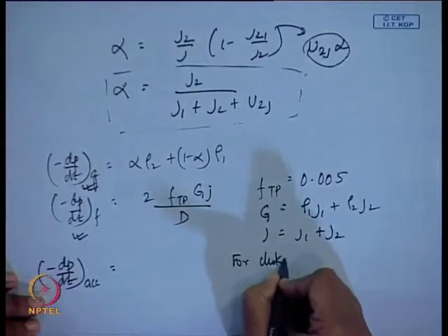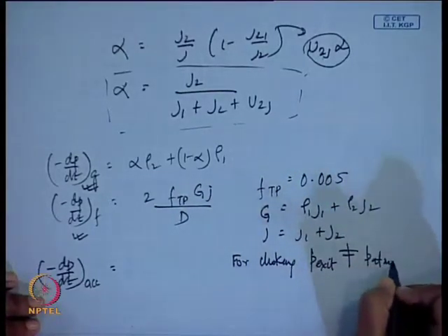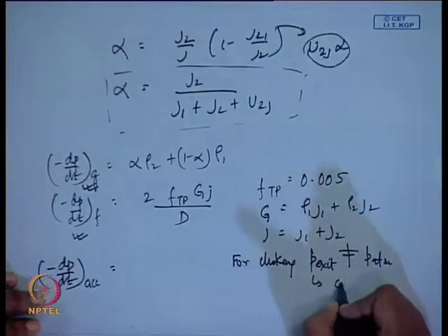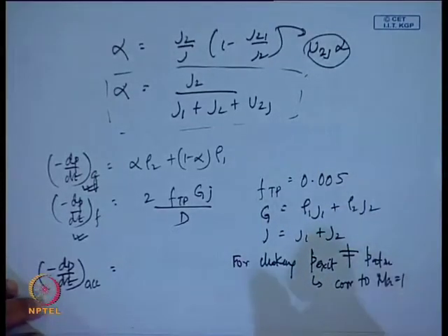In the mid-sem also I had given you a problem with a catch, and most of you could not get the catch, but remember these things are very important. So, you have to keep it in mind when you proceed: just check whether the flow corresponds to sonic flow or not, whether there is choking or not. If choking is there, for choking I will write down, P exit will not be equal to P atmospheric. Okay. So, P exit will correspond to Ma equals 1. So, these small things you are supposed to remember.